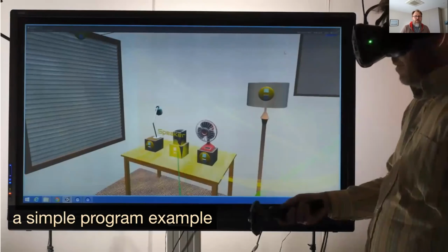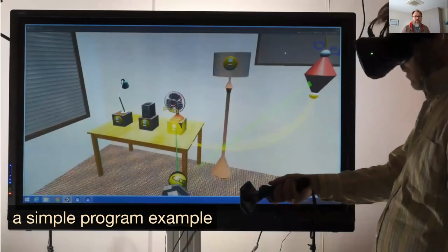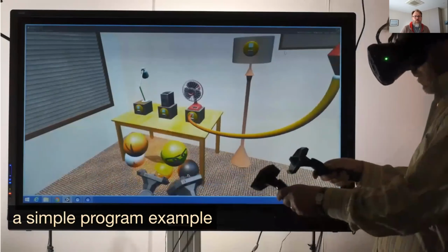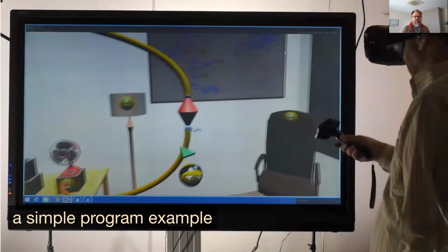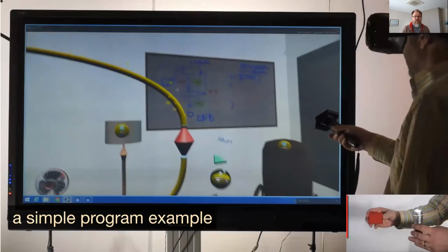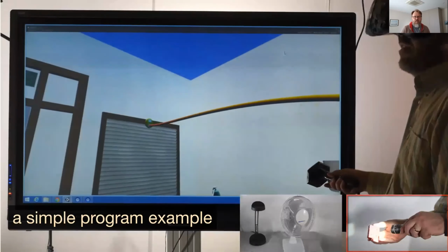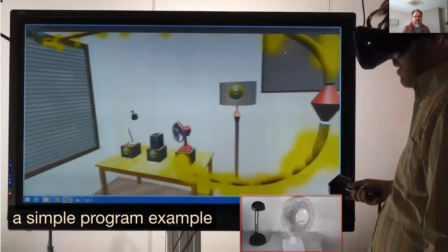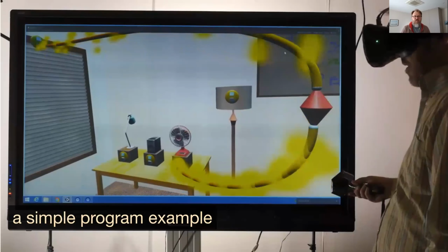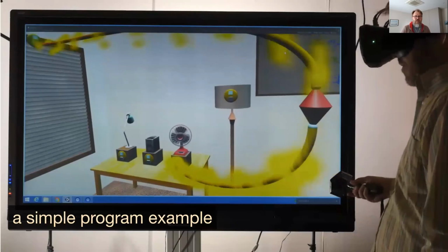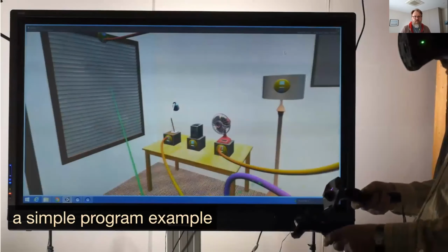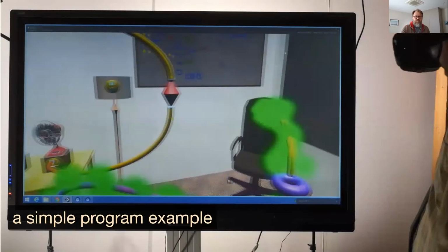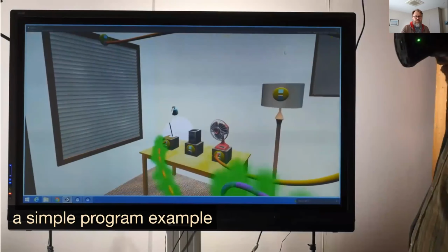But the interesting part is you can take that trigger output. If a certain condition is met, if the light is over a certain value, then it's going to turn on this fan. If you look in the lower right-hand corner of the video, I'm going to press run, and here's one of the TI tags I mentioned. I'm going to shine a flashlight on the light sensor, and you can see the data values increase, and lo and behold, they activate the trigger and the fan turns on. We actually had a physical fan in the lab that would turn on when this happened. So that was quite cool to see the actual physical result of this.